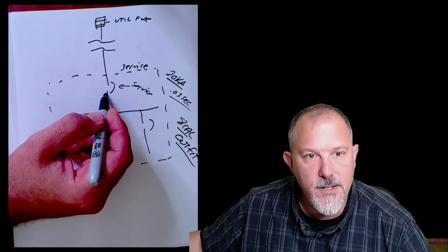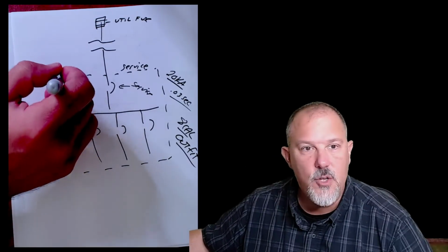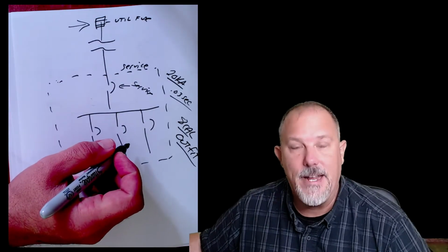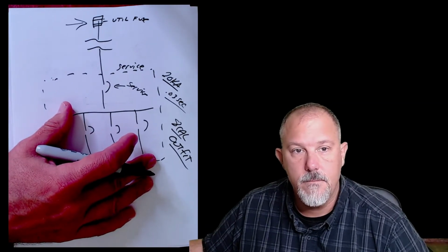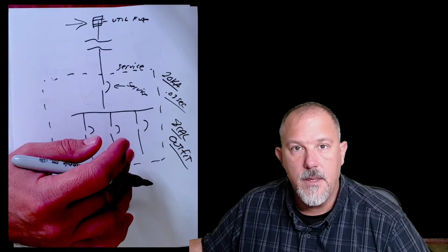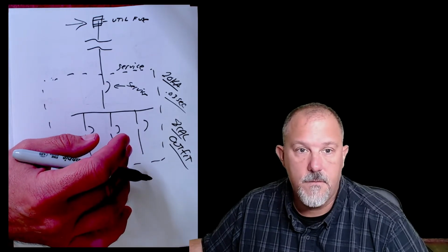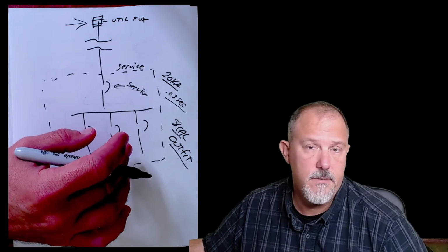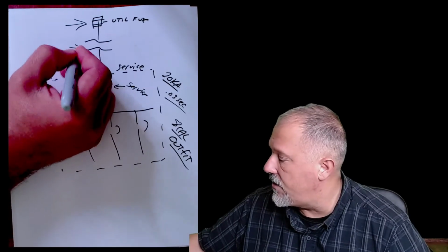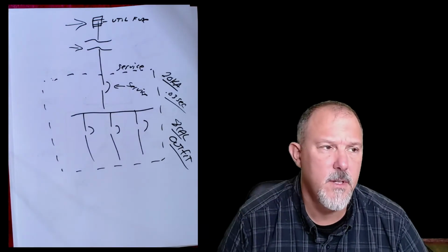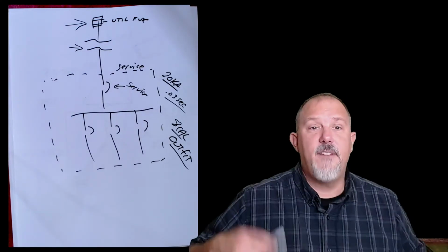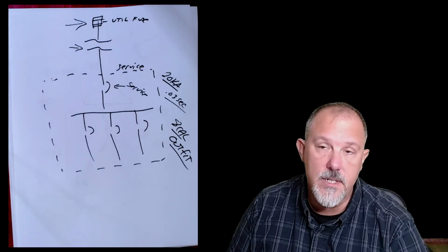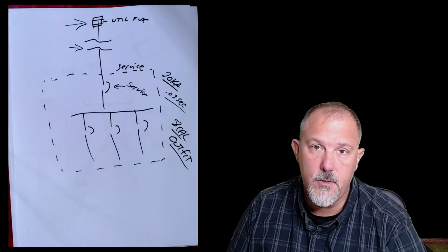But because my incident energy of this equipment is based upon the clearing time of that device, this could be 40 cal, it could be 100 cals, depends. Depends on how much fault current, depends on the size of that transformer. Because I have to rely on the upstream overcurrent protective device. And that wasn't clear in the 2020 code or earlier.